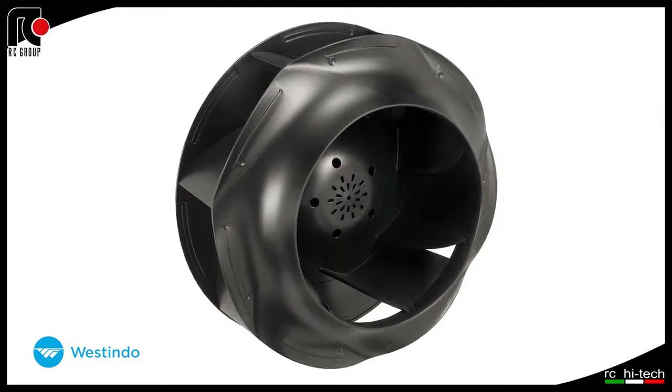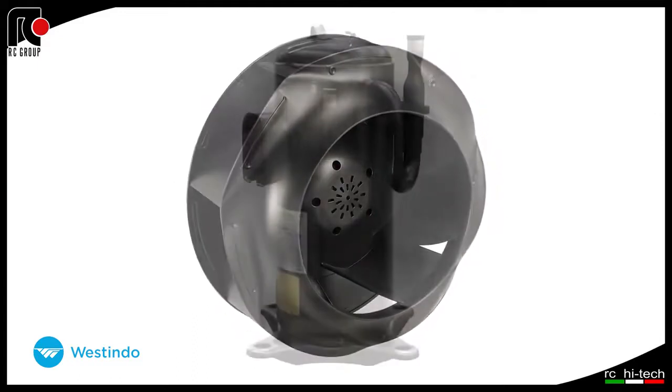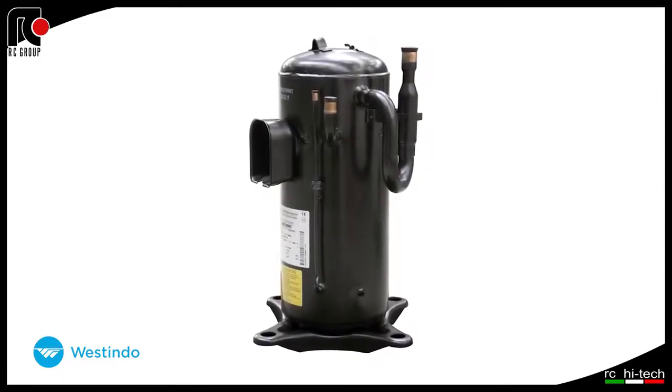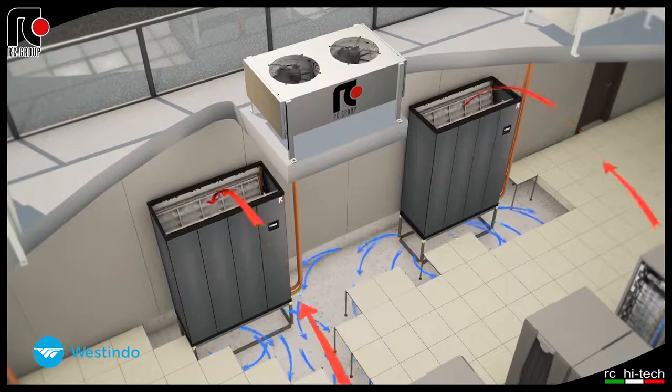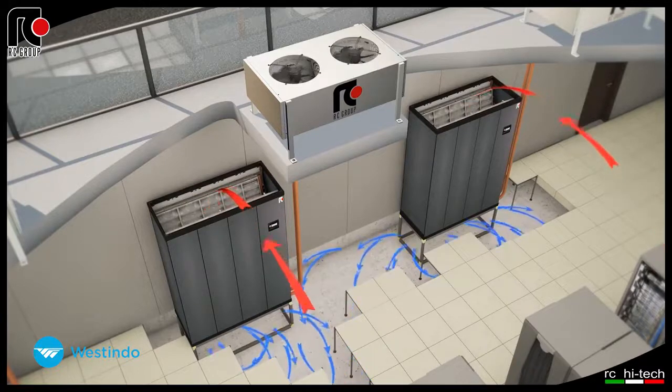Main components for each air conditioner are EC electronically commutated plug fans and inverter-driven scroll compressors with stepless capacity control. The combined operation of the inverter-driven compressor and EC fans responds in real time to thermal load changes within the data center and realizes substantial energy savings.